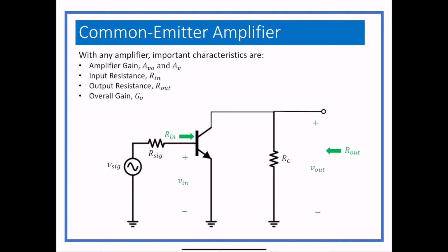So the first thing we're going to do, last time we talked about the different models that we have. We have a transconductance-based model, but we also have models that are based on alpha or beta, depending on how we use them. And for the common emitter, we're going to use the transconductance-based one, and you'll see that the answers that you get are almost exactly like MOSFET. With the others, we're going to use a bit of a different way of looking at them, just because this is kind of how the circuits end up working out more simply.